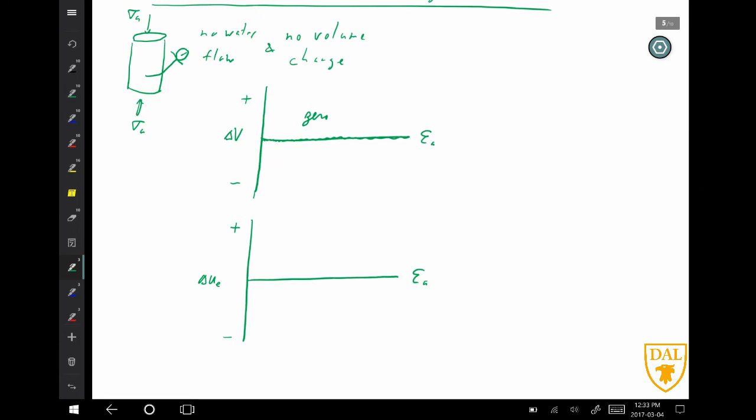Now the pore pressure is a little bit complicated, and it relates to, in some way, the volume change characteristics of the drain test. So, in the sand-like material, granular materials, we had two cases, loose and dense. The analogous conditions for a clay-like material, if you remember, is really about its consistency, whether it's soft or stiff.